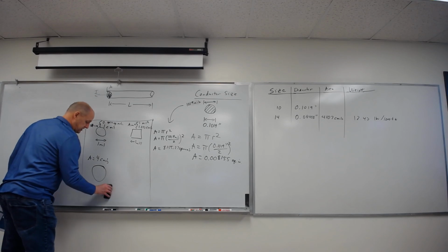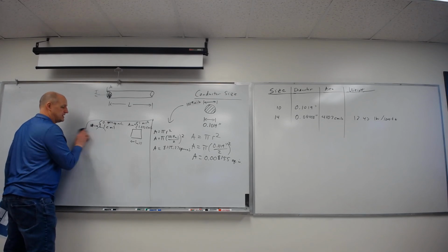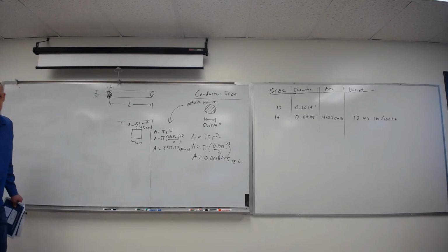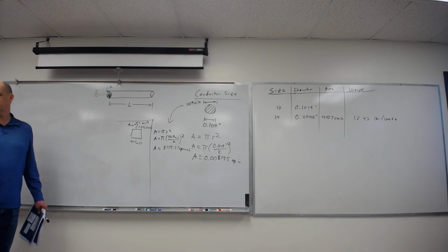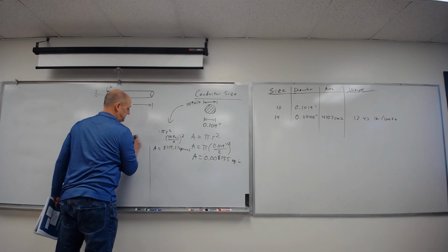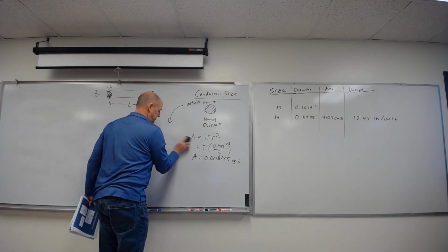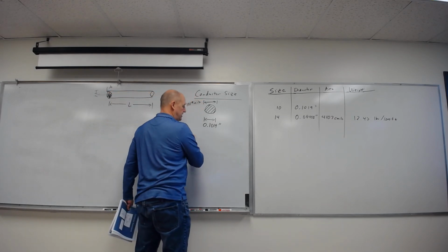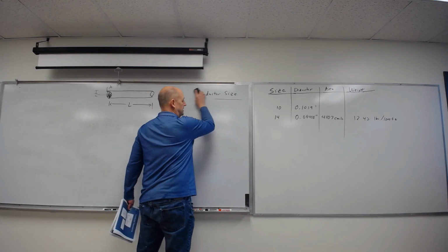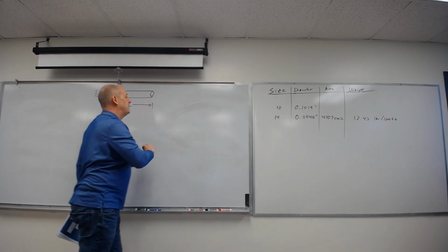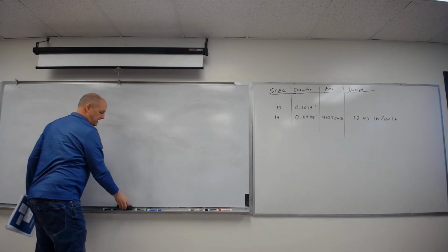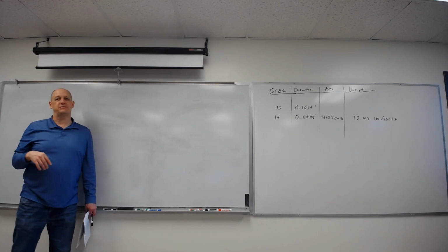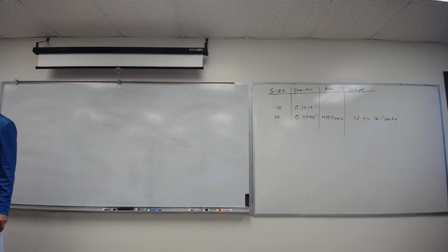10. The small little wires we use in here, I actually don't know what gauge they are, but they're probably somewhere around 22, 24, 26, somewhere in that range. If you're inside a piece of electronics and it has some power, it's probably going to be something like 18 gauge. This also does not address the fact that it's a separate issue, that most wire you're going to use inside, well, those little jumper wires are single strand, but a lot of times for connection wires for higher power, you'll use stranded, a whole bunch of stranded.